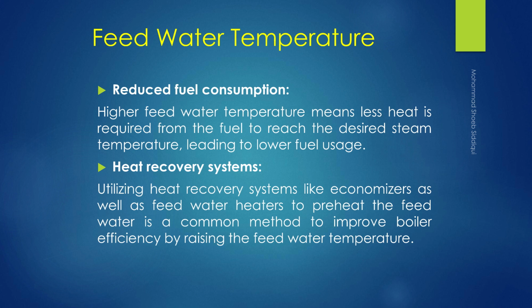Heat recovery systems. Utilizing heat recovery systems like economizers, as well as feed water heaters, to preheat the feed water is a common method to improve boiler efficiency by raising the feed water temperature.